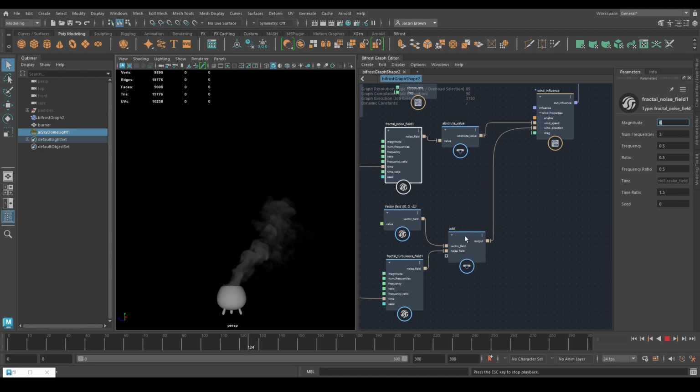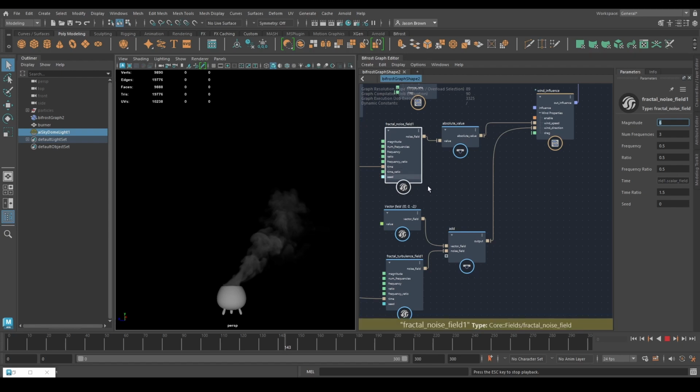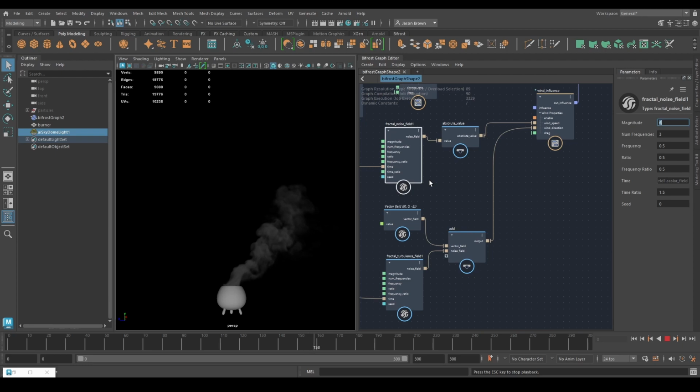It saves you time, and it sounds stupid, but it stops you from getting confused, because if I changed the wind speed, the wind direction, the turbulence field, the way that it was generated, what its voxel fog density was, and I got something I didn't like, then I would have absolutely no idea which one of those settings made the thing I didn't like, right? So that's just something you need to bear in mind when you're working with anything simulated. So that's particles, smoke, fire, NPM, which we're going to get to shortly, explosions, which is what we're doing next week, things like that.